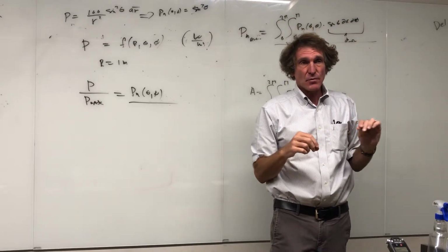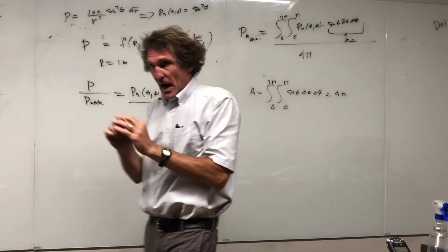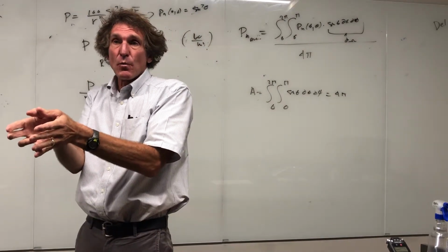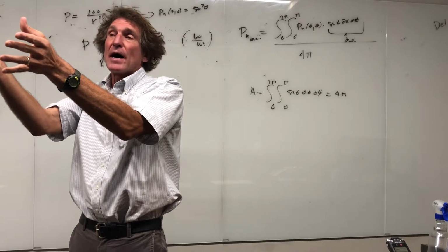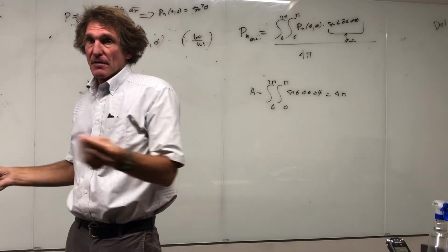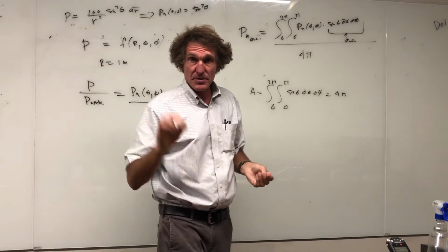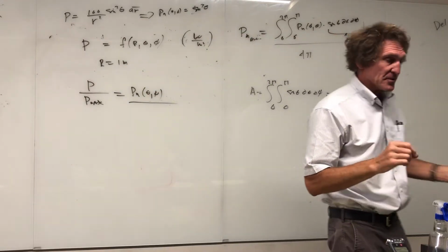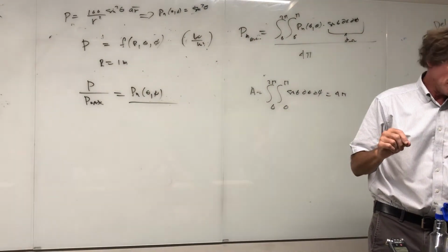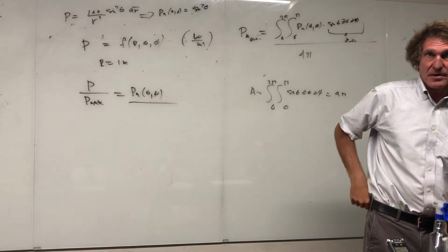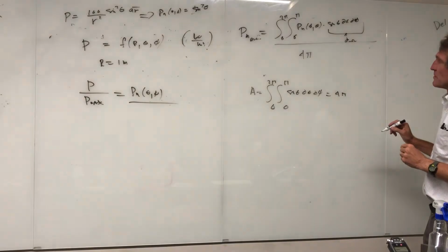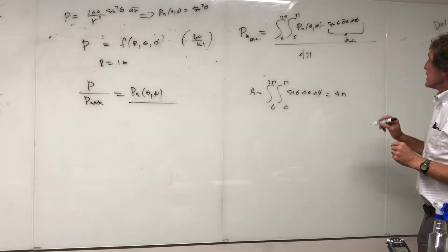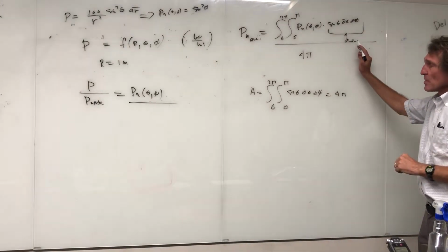So oftentimes with radar and things like this, they say, as far as the main beam, how many steradians are in there? That gives them a real good idea of how actually focused it is. If you got almost nothing, it's like a pencil. It's called a pencil beam antenna, like a laser just about. And there you can get something close to that, but you can never get everything directed in one direction. You can't get a pure pencil beam with anything but a laser. So that's just the omega, but you don't need to worry about that.